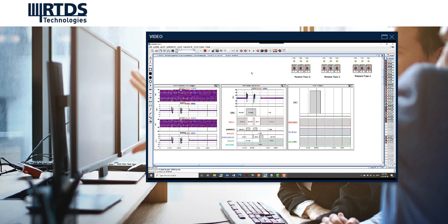So we can see that the recloser's instantaneous overcurrent element has detected that fault and initially tripped the breaker. And then it sends its first reclose command back to the breaker, but the fault is still persisting, so the breaker closes back onto the fault, causing that instantaneous overcurrent element again to issue its second trip signal. Then we have the second reclose issue, and that reclose is successful as the fault has cleared.